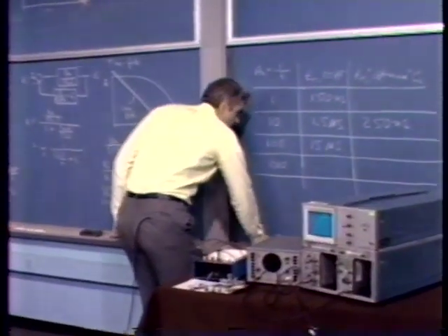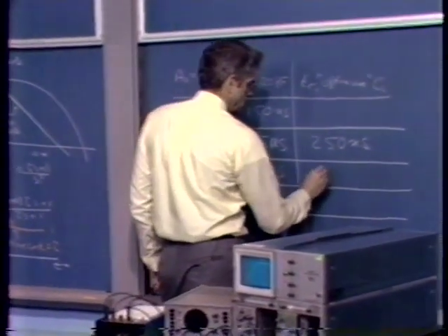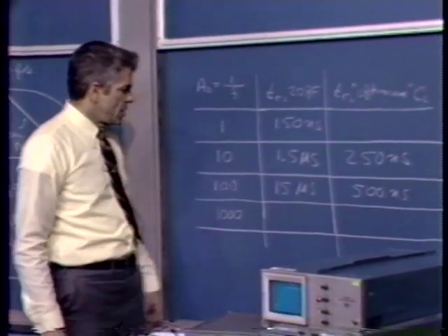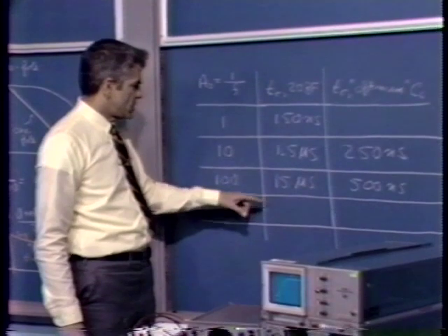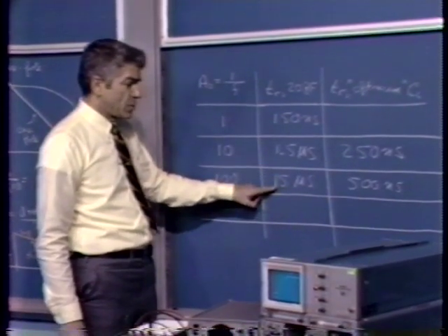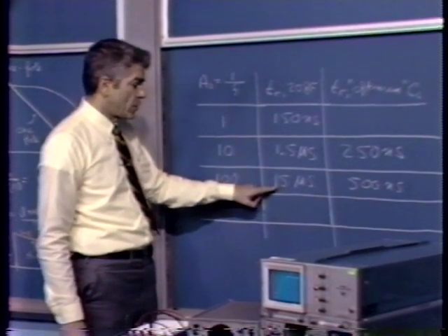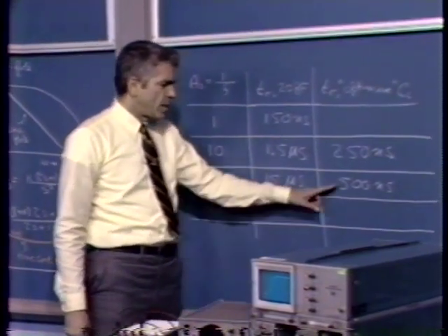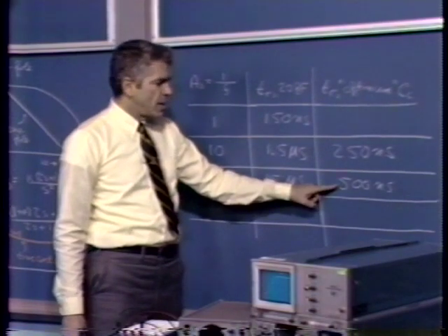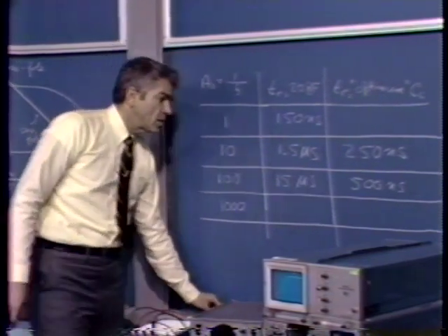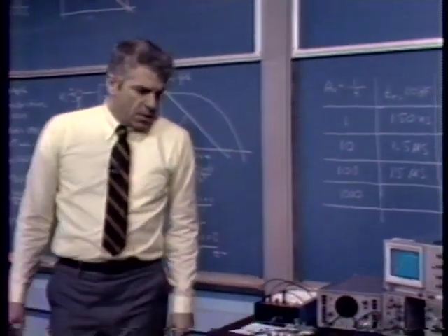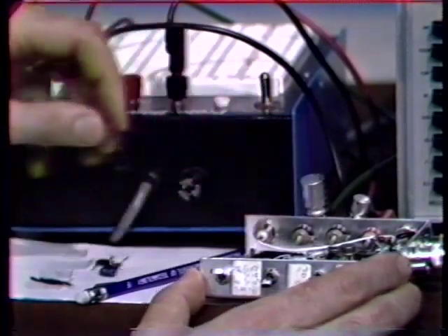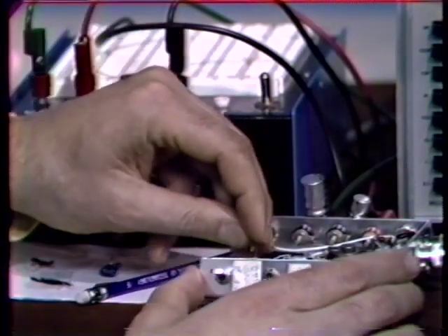So again, we haven't quite gotten back to the original case, but we're roughly a factor of 30 faster than the case that resulted when we used the capacitor that was selected for unity gain stability or for unity feedback. So we've made a very, very dramatic improvement in the bandwidth of the amplifier by simply choosing the compensating capacitor as a function of the closed loop gain. Finally, let me go back to the original value, the 20 picofarad compensating capacitor, one last time.